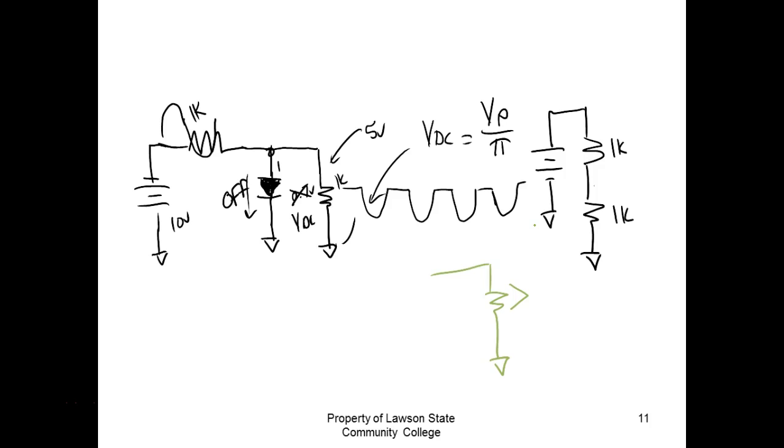There's no parallel circuit here. If the diode is forward biased, then we end up with a 1 resistor series circuit, right? If it's reverse biased, we end up with a 2 resistor series circuit. So this would be the equivalent circuit. If it's forward biased, we end up with this; if it's reverse biased, we end up with that. There's no parallel circuit.